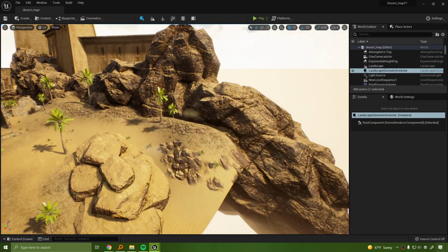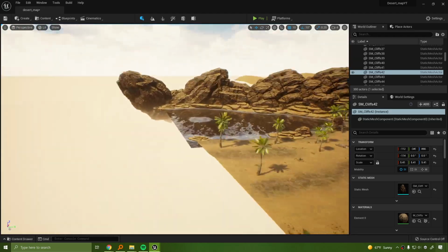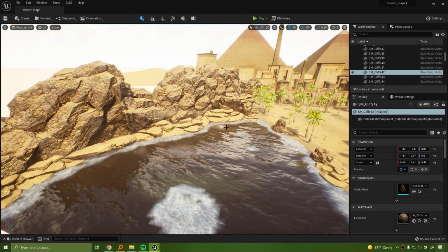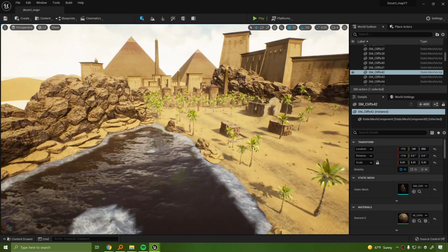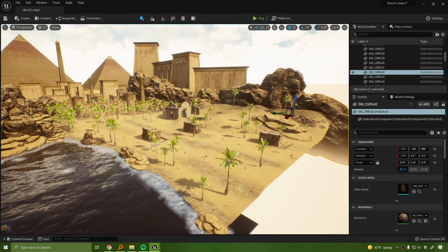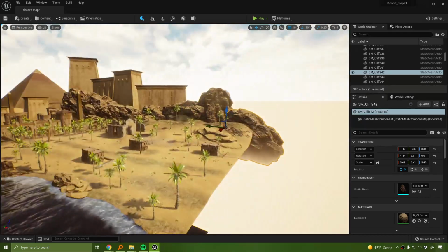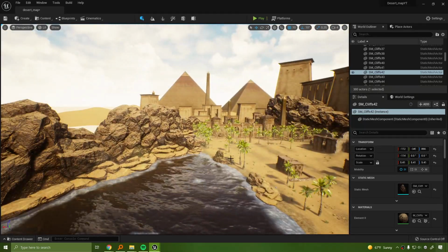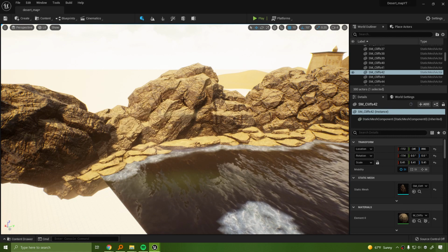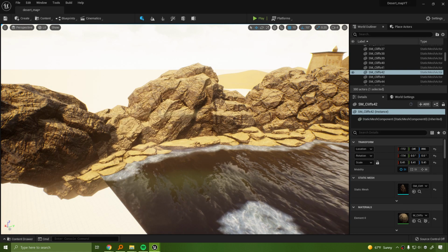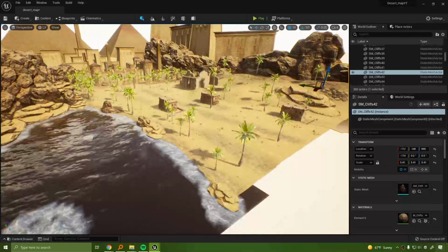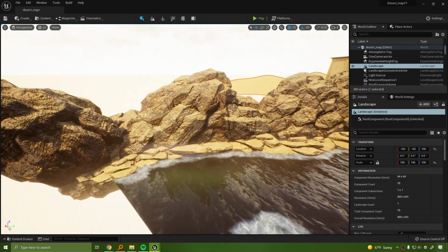Ms. Figueroa, why don't we just sculpt things like this? The reason we don't use the landscape tool to sculpt absolutely every element of the environment is, simply put, the landscape system is mostly just a placeholder system to allow us to create a vast level of detail and a vastness that is supposed to be the quote-unquote landscape. It does not have the capacity to do sculpts of this particular level. You can get something pretty convincing if you spend a lot of time, but if you're going to be spending a lot of time sculpting these kinds of shapes using the landscape system, you are essentially just wasting your time.